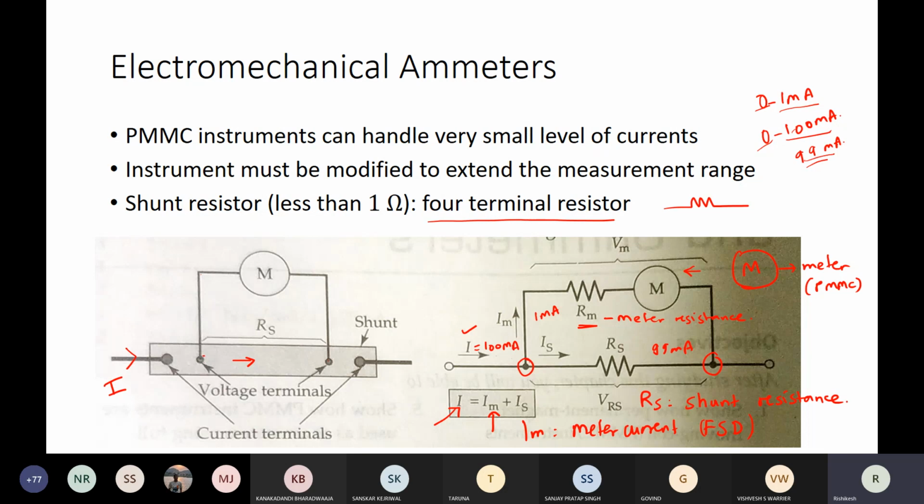Remember, when the current flows through the circuit, these are conducting elements. There will be a heating effect, which will cause a change in the resistance itself, isn't it? So if the change in resistance occurs, that is Rs tends towards Rs dash due to current flow of I and the heating effect, the entire calculation will go wrong.